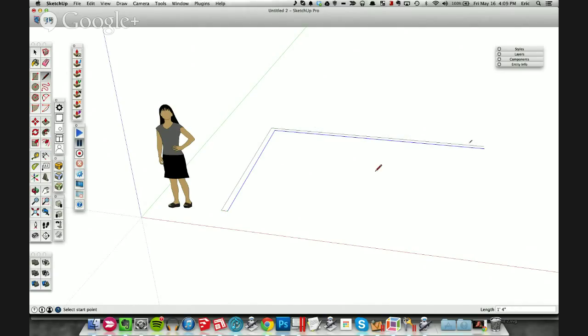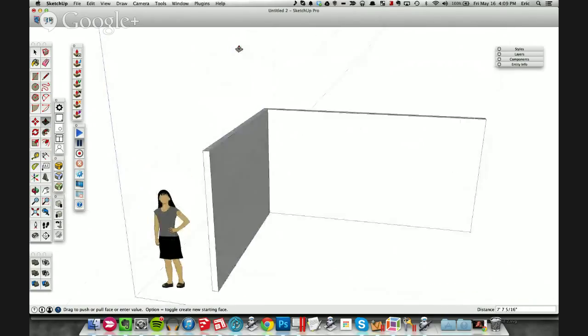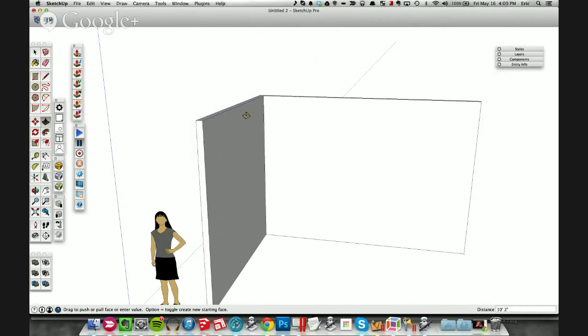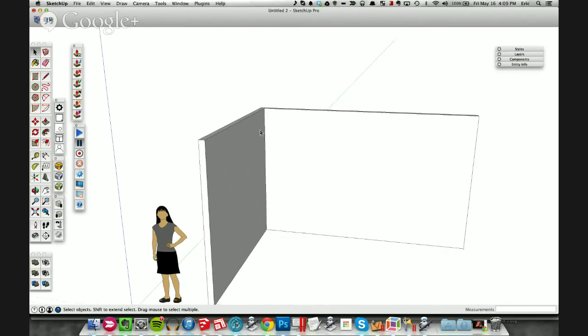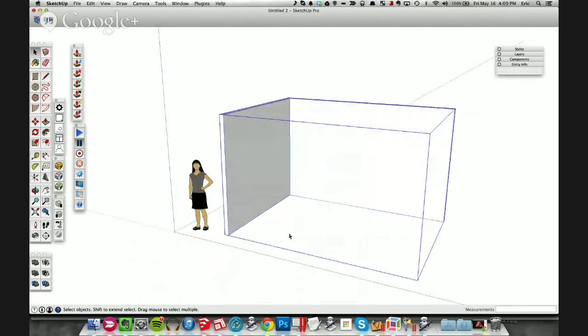Once you have a group of lines that are all connected, like this one, you get a face in SketchUp. And you get to use the famous SketchUp push-pull tool, which takes a face and makes it into 3D like that. So you can see we've drawn 6 lines, and we're already into something 3D. This is a fancy house, Lori, so we're going to say it's got 9-foot ceilings. Now we've got our 3D wall here with 9-foot ceilings, and I'm going to put it into a group.